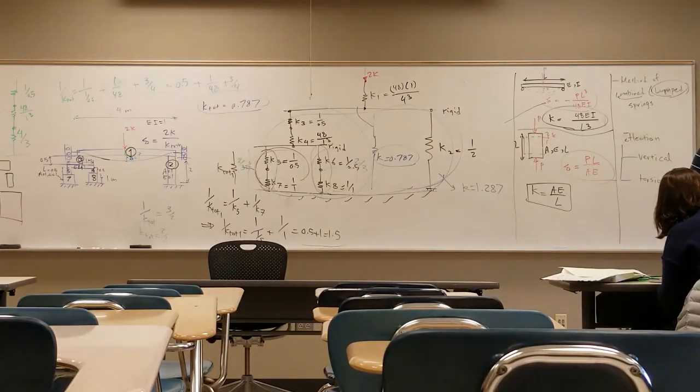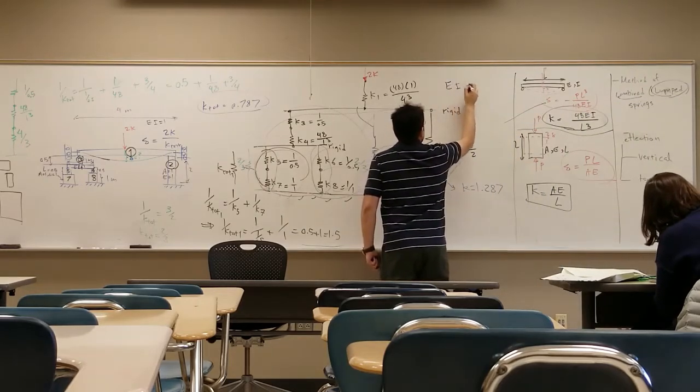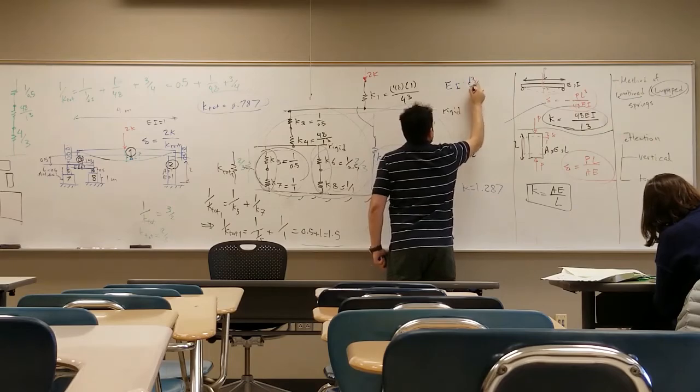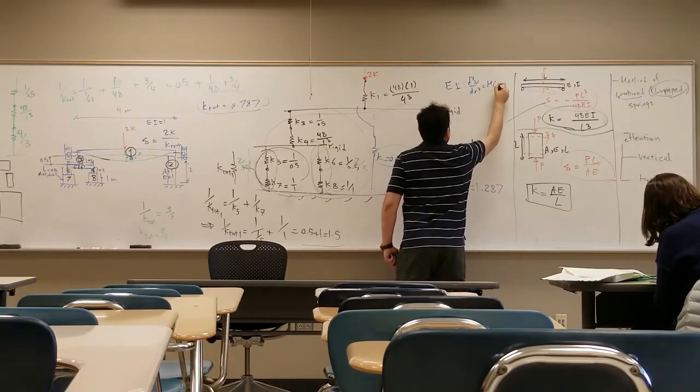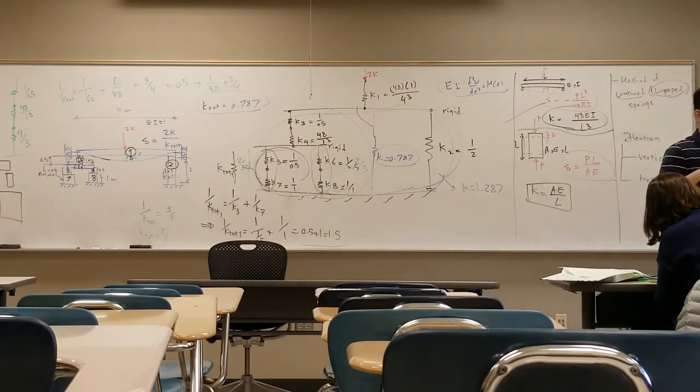Is there a quantitative limit on deflection that we can use the double integration method with? Like, is there a number after which it's less accurate? You can derive that number. In fact, you can derive it if you know how to derive this relation: EI times the second derivative of v is equal to Mx. The derivation of this is given in mechanics of materials, of course.